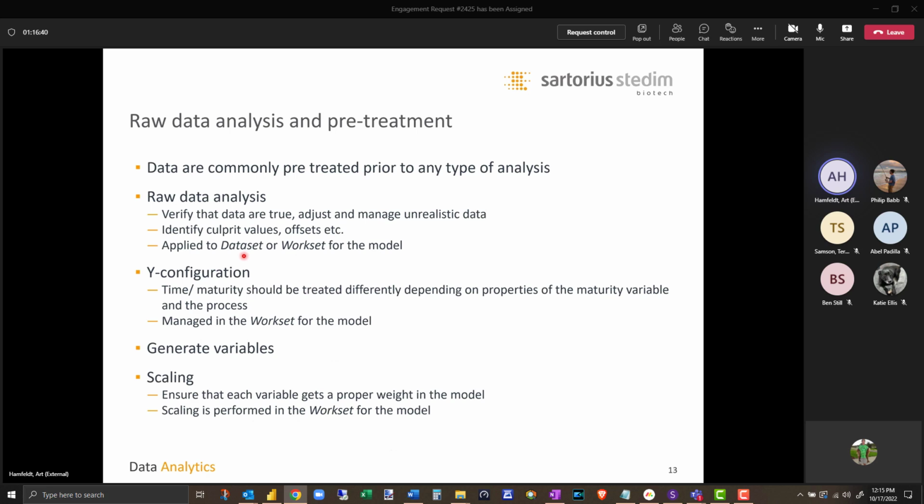Then go ahead and go, okay, when flow is equal to 0, so you collected all the data, you have it in Excel, and you're like, I'm not going to clean it up in Excel. I'm just going to import it into Simca. Once you have the data set in, you can just pull up that on-off flow and delete all the rows at that point in time. And now you have a nice clean data set to work with. So that is a valid use. I do that quite a bit because I'm just lazy.